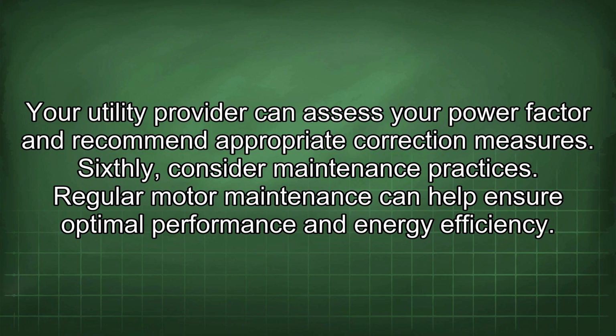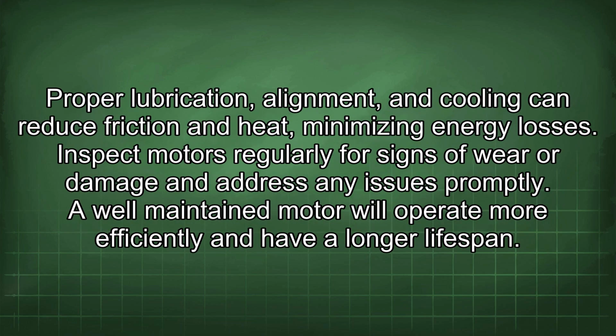Sixthly, consider maintenance practices. Regular motor maintenance can help ensure optimal performance and energy efficiency. Proper lubrication, alignment, and cooling can reduce friction and heat, minimizing energy losses. Inspect motors regularly for signs of wear or damage and address any issues promptly. A well-maintained motor will operate more efficiently and have a longer lifespan.